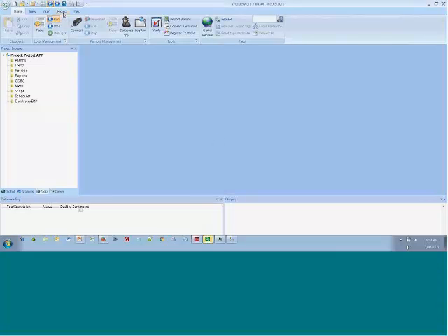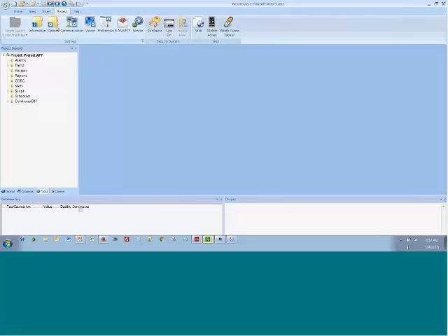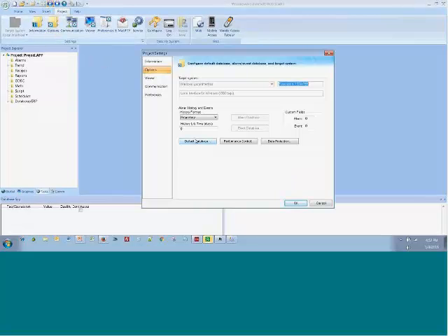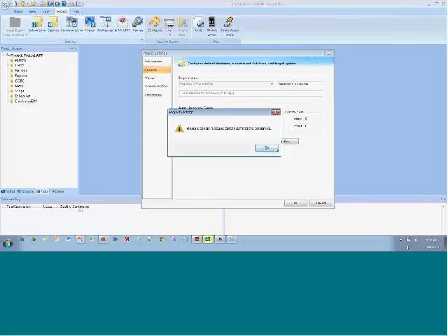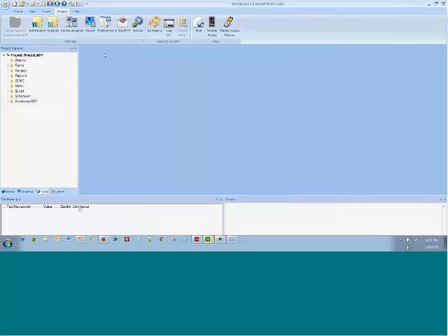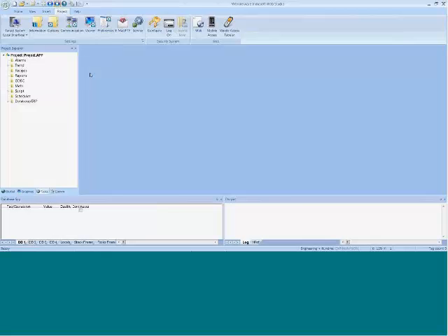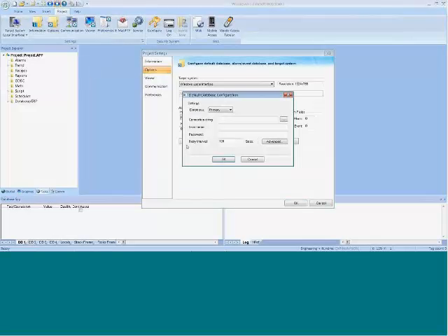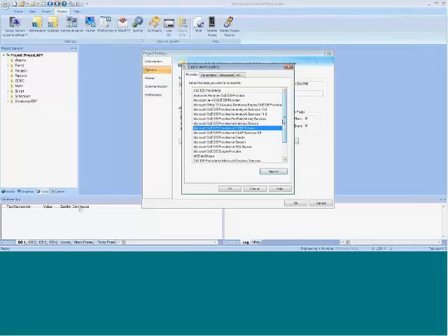And then what I'm going to do is go here under Project and Options, and I'm going to set up a connection to the default database throughout the entire project. And I have to have my project stopped first. Sorry about that. Set up the default connection. Now, if I knew the connection string and how to get to that database, I could type it in here, or I could put a string type tag in here and make it flexible and changeable during runtime. Or I'm going to use this little wizard here that will allow us to configure this if I don't really know what I'm doing here.